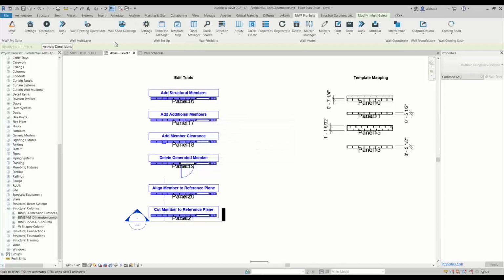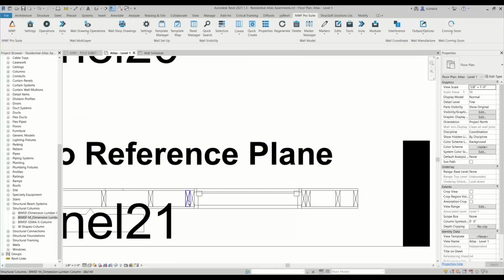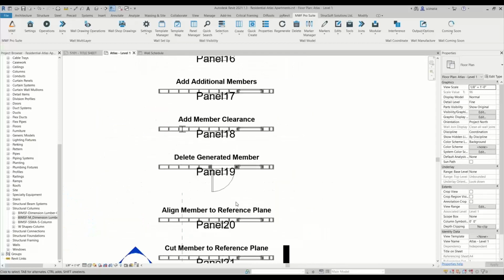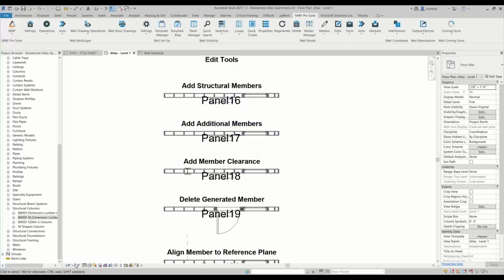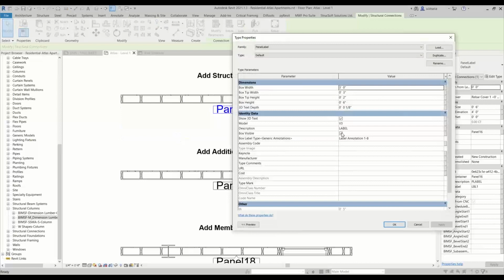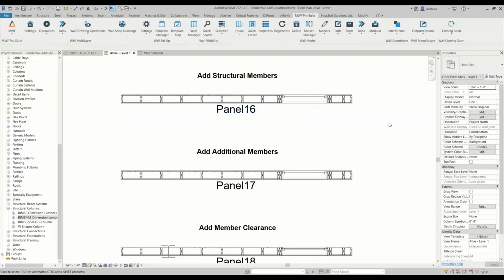All right, so now that we wonderfully quick created all of our walls, you can see that it actually framed my openings as well. If I had any markers assigned to them, it would automatically read those markers and frame the openings according to that. Let's make the scale for this a little smaller, just so that we can go through them faster. And I'll also get rid of the box visibility for the panel labels. There you go.